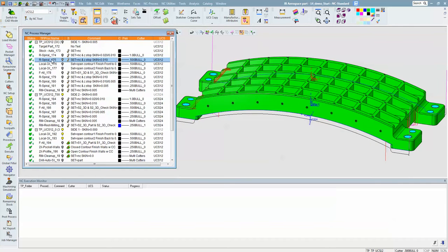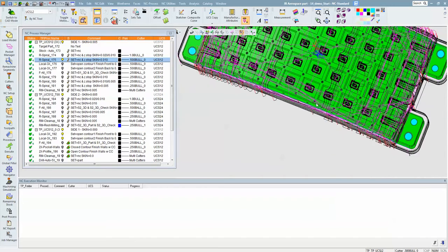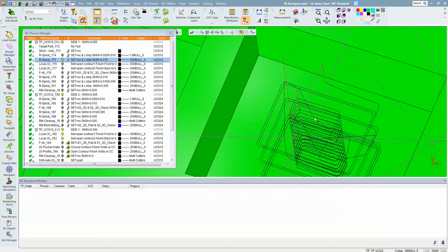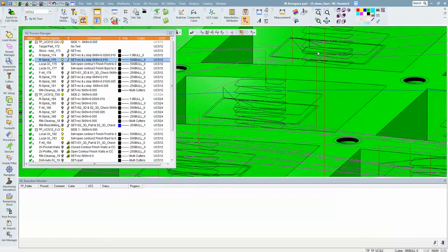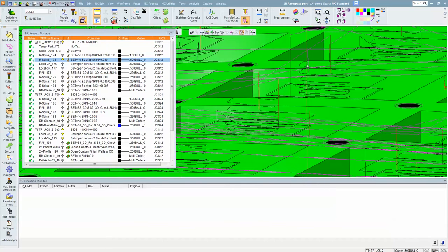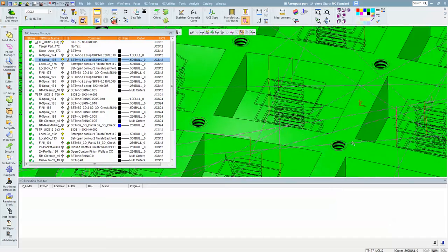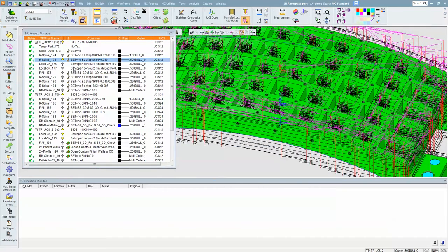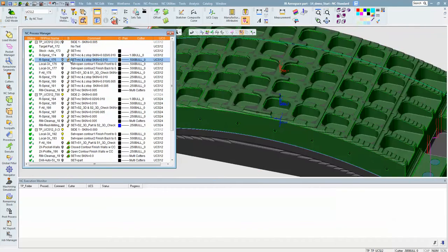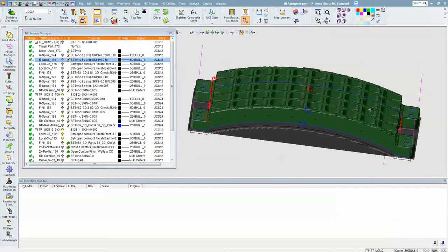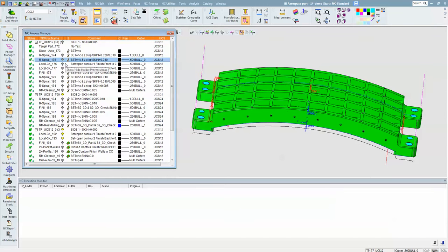So here, when we go to a 1/2 inch cutter, we'll see that that's getting into these pockets now, and it's going to be doing ramping motion. You can kind of see it here. We can set the ramp angle, and it comes in and roughs these pockets out. And if we look at the remaining stock after this one, it's going to look like that. Alright, these local 3X are the ones that we just looked at.